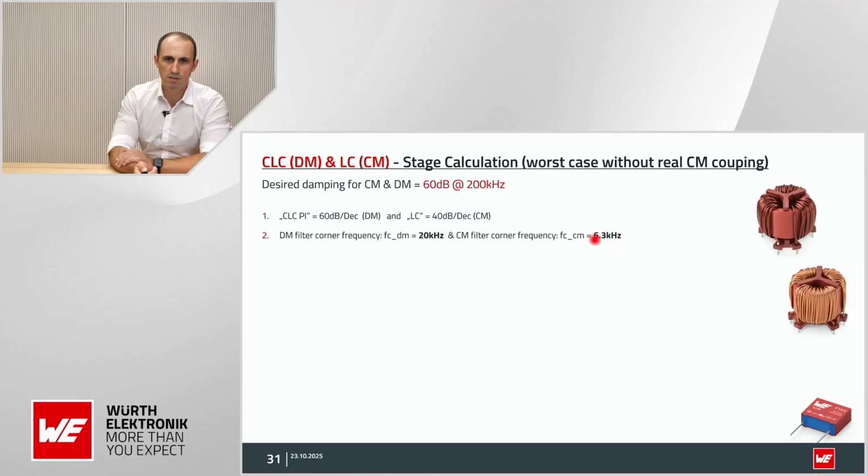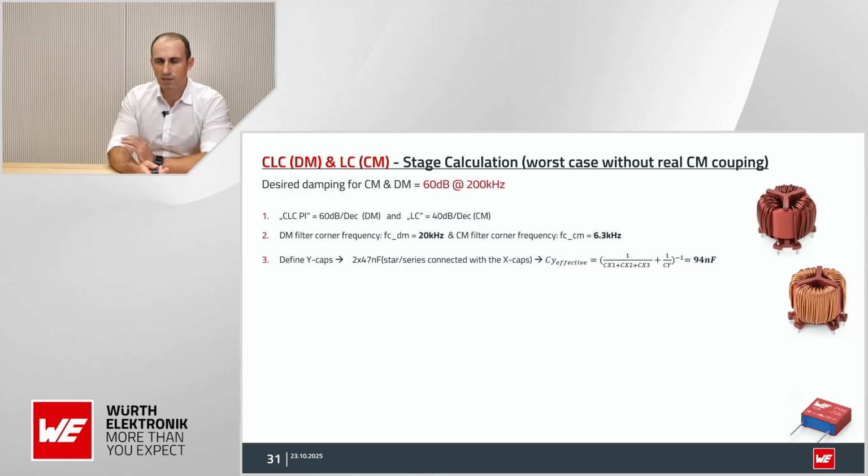Therefore, the components will result in bigger values after all. Okay, we have to start with something. Therefore, we have already defined the Y-caps because they are safety relevant. We cannot put in too big Y-caps due to the leakage current. So we just calculate with the bigger Y-caps, because the smaller ones play no big role here, but you can also, of course, put them together.